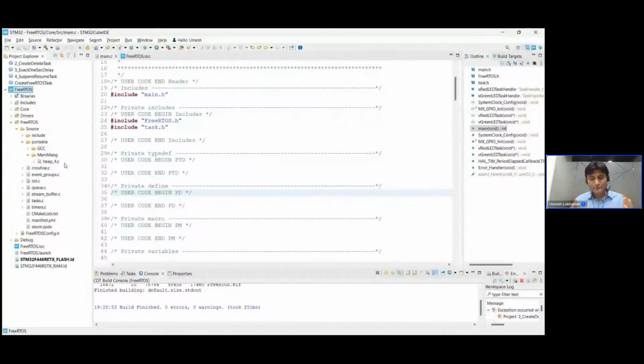So when you use FreeRTOS, you have four different memory management schemes available to use. So there is heap 1, heap 2, heap 3, heap 4. And look, in my project, I'm using heap 4. You might see a lot of projects where developers often use heap 4. I don't mean the other memory management schemes are not useful, but most of your purposes of writing application code get served by the heap 4 memory scheme. Okay, that's why it's very common and generic.